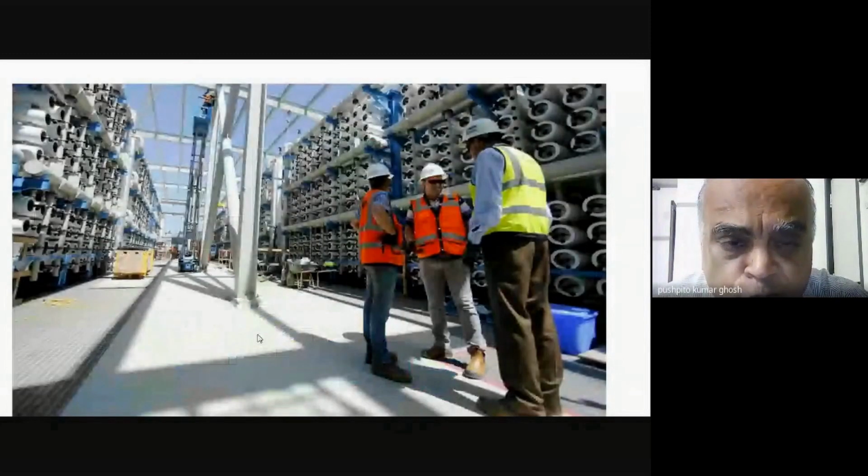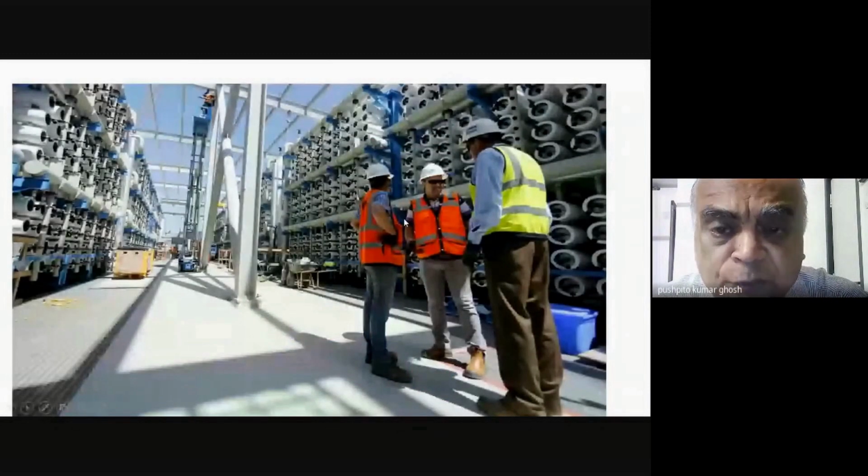Now, just to show you a large plant, look at the size. Each of these that you see is a membrane element, and there are thousands of them. The modules are connected mostly in parallel and some in series. What you have to remember as an engineer is that it is not uncommon for some of these modules to go bad.